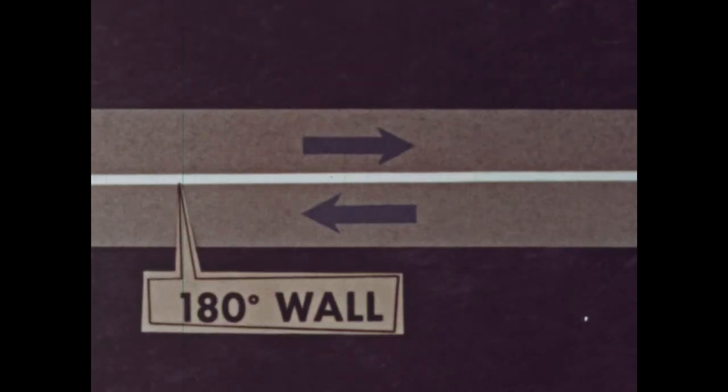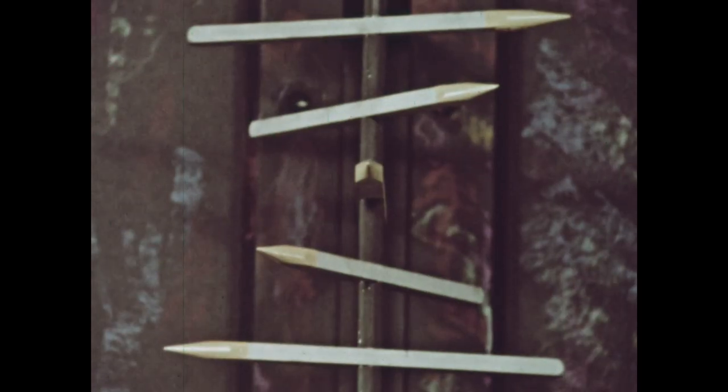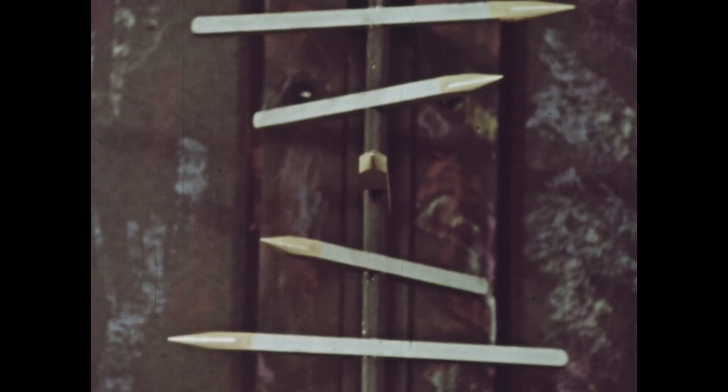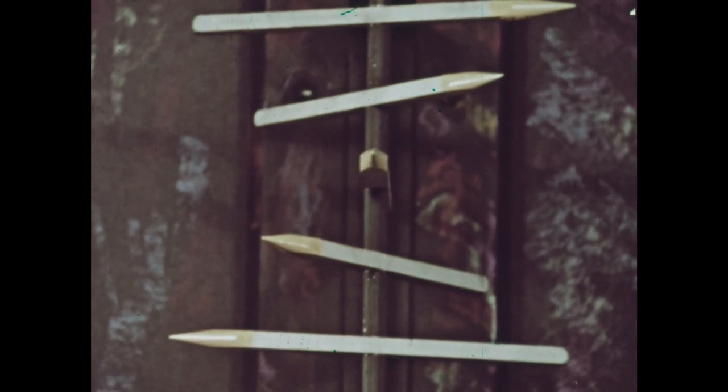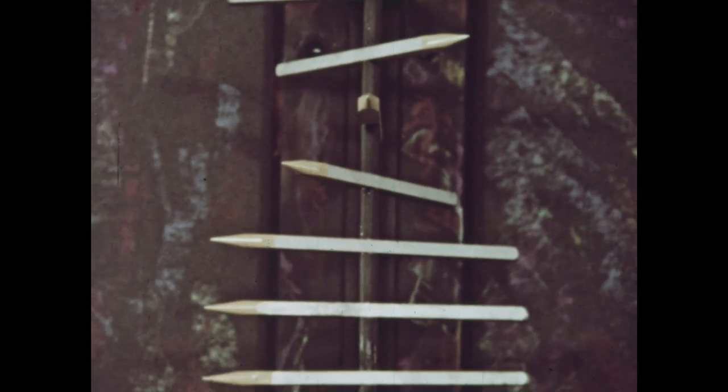However, the direction of magnetization does change in the following way. Let us put a 180-degree domain wall into the specimen. As its name implies, the moments within the wall rotate through 180 degrees. The wall has its own minimum energy per square centimeter regardless of its position.